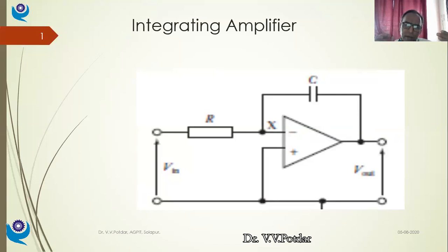My transducer can sense the temperature within the system, convert it into equivalent voltage form, and send it as a feedback signal. And corresponding to 300 degrees Celsius, I have got some voltage signal. That voltage signal is to be compared with the feedback signal. In that case, 3 volt minus 2.5 volt, so 0.5 volt is the error. Maybe it corresponds to 50 degrees Celsius.